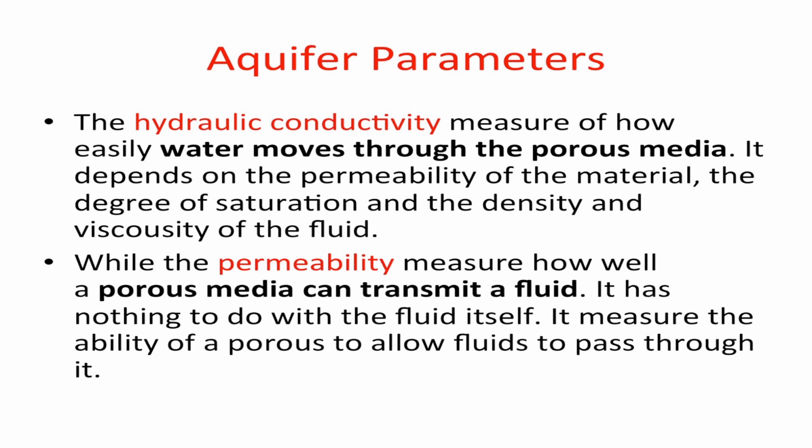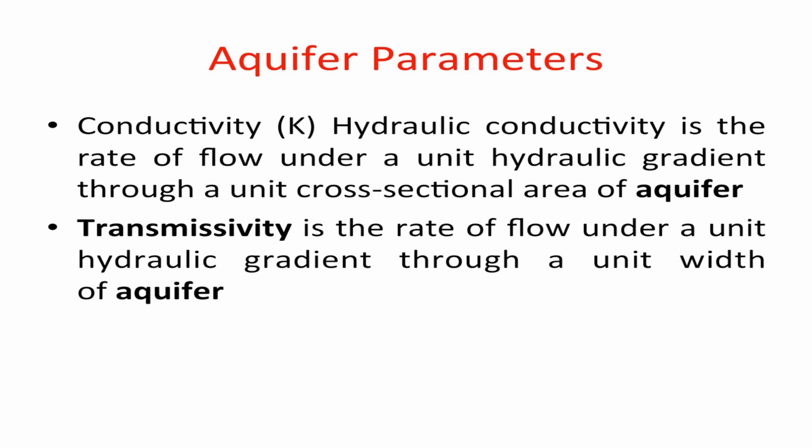While we are talking about hydraulic conductivity, next we can compare it with transmissibility. Hydraulic conductivity explains the transmittance capacity of the medium. Transmissibility also explains the rate of flow, but it considers the depth of the aquifer. So transmissibility is nothing but the rate of flow under unit hydraulic gradient under unit width of aquifer.